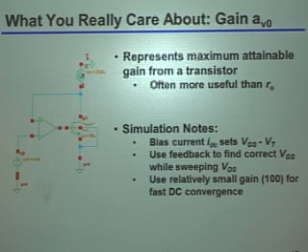So in other words, to say it another way, what I'm really truly fixing here is not necessarily the V star, but rather the bias current density. But at least once you fixed VDS, the bias current density, meaning how much current you had flowing per unit width of the transistor, is very closely related to the V star. In other words, for a fixed VDS, there's a unique bias current density associated with each individual V star. And you're right, as you change the VDS, the V star or the bias current density would change somewhat. But again, this is to zero order going to tell us pretty darn close to exactly what we really care about. Does that answer your question?